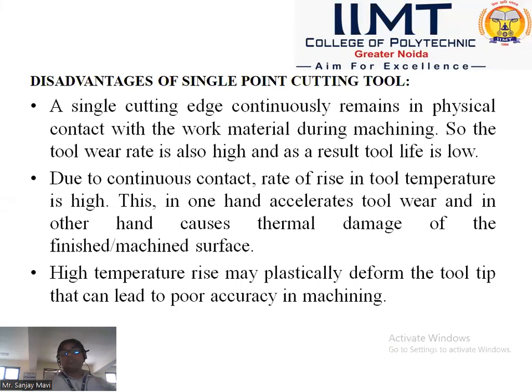These high temperatures can plastically deform the tool tip, and that can lead to poor accuracy in machining. If the temperature of the cutting tool tip increases beyond the permissible temperature, it will negatively affect the workpiece and cutting tool.